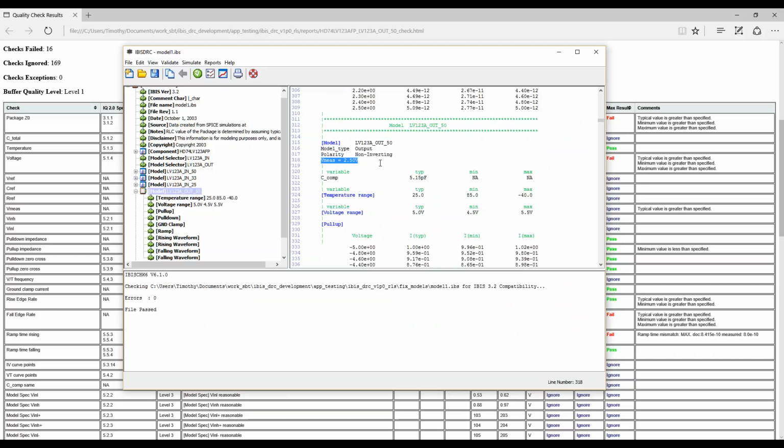They might use a capacitor to ground, and then you measure the time it takes the driver to cross this threshold. So this Vmeas value is in here, but what's not in here is the timing load. What's going to happen is some tools are going to interpret this as being an open.